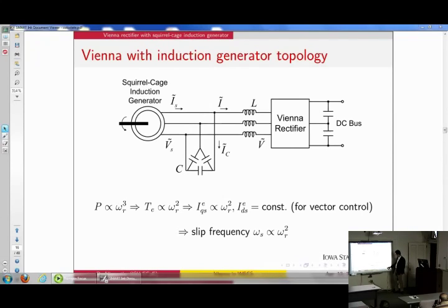So why is this popping up? Okay, with this in mind, think about an induction motor that you learned about in high school, maybe. It has an equivalent circuit. You can solve the equivalent circuit for any wind speed, because if I give you the wind speed, you know how much power you're supposed to produce at that wind speed, and at what speed you're supposed to produce it. So you know everything there is to know about this equivalent circuit, the slip and all those things, and so you can solve it for a range of wind speeds.